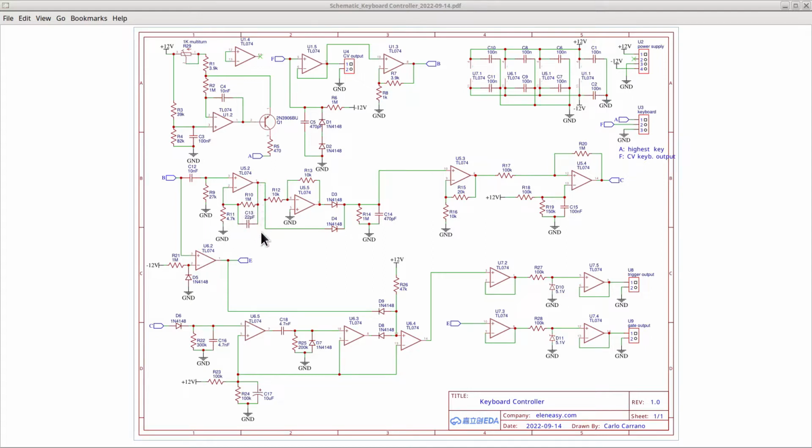And now, this part is basically identical to the one from the previous design. Since I have pulses that are both positive and negative, I add an inverting amplifier that inverts the voltage of every pulse. Then I use two diodes, D3 and D4, to catch all the positive pulses from the two op-amps U5.2 and U5.5. These are all the pulses present at the HP filter output, but all with a positive amplitude.